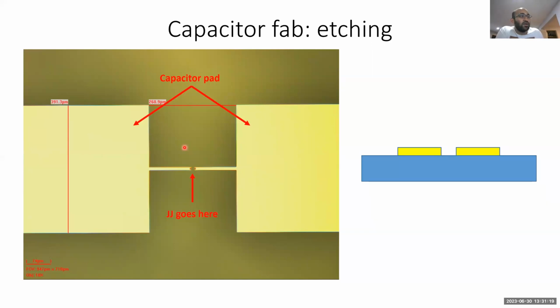If you have too much mechanical etching in your RIE, so if your RIE powers are too high, then your ions will have a lot of kinetic energy and can actually mechanically etch your substrate. For silicon, if you're doing a fluorine process, silicon is also vulnerable to fluorine-based processes.